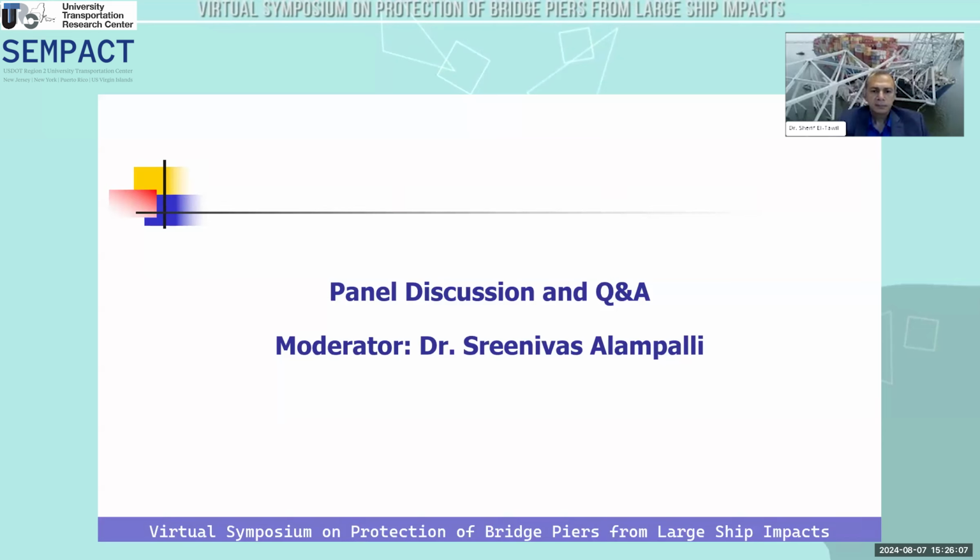Well, to continue on this line, I would also say that if you have these oblique impacts, then of course you should take into account that the vessel can slide, and dependent on the coefficient of friction between the vessel and the concrete, you can have different transverse forces. But you should take into account the swaying of the vessel and its added mass from the water, because then you reduce the impact to the pier quite considerably.